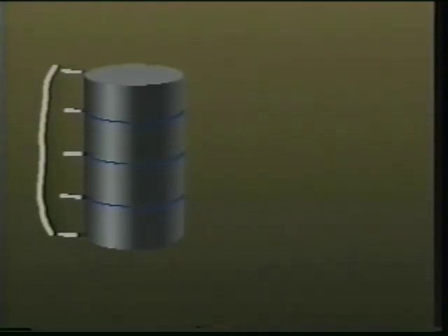The rate at which the level rises is affected by the geometry of the tank. For example, let's consider a cylindrical tank. As the level climbs, the surface area remains constant, and thus the rate of change in the level remains constant as well. If the diameter of the tank were smaller, resulting in less surface area, then the rate of change in level would be greater for the same rate of inlet flow, but would still be linear in nature.